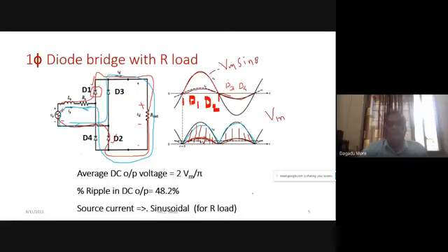And then we have to integrate this. So we are having two pulses. So our average voltage expression VDC, it is not necessary to go over everything. We can write VDC will be equal to 1 over 2 pi times 2, since we are getting two pulses in the period of 2 pi, and we have an integration from 0 to pi.